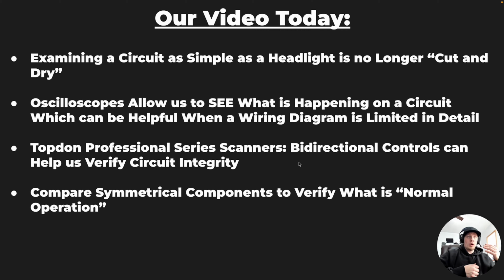One of the other things you want to keep in mind that's really valuable and can help you out in your diagnostic process is the bidirectional control feature on the Topdon Pro Series tools. This can really help you test a circuit without having to go inside, operate the switches, or put the vehicle through another specific criteria in order to operate a given circuit. Oftentimes the bidirectional controls will allow you to turn something on or off and monitor that circuit using other tooling like the oscilloscope.